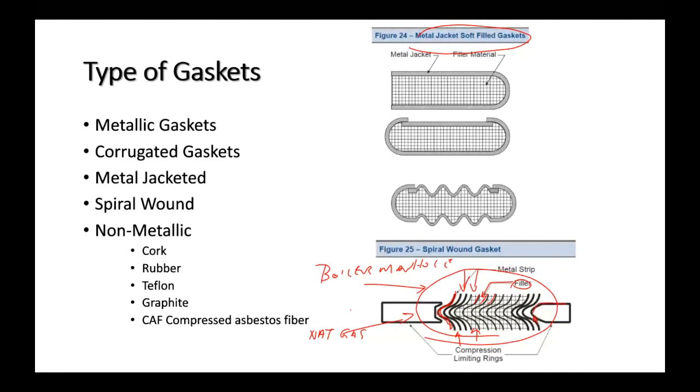And there are some solid rings that go all the way around the gasket that are there to prevent you from over tightening. So you can compress it until you get to that thickness, at which point the gasket will compress no more. You don't want to over compress it. But my one word advice to everybody with gaskets is gaskets are single use. It's not like they cost you $800 a piece. Once they are compressed, they lose their resiliency.